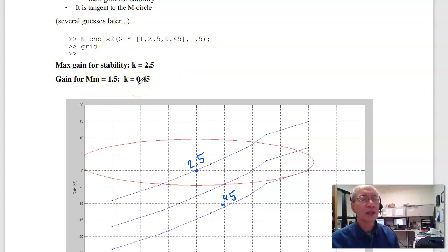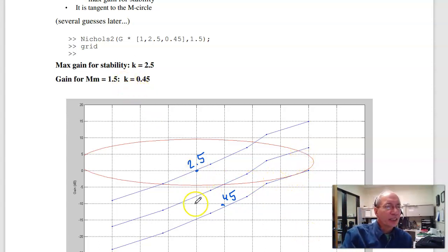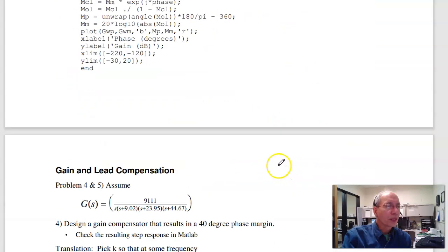Again, this is the beauty of Nichols charts. I don't need the transfer function. I don't need any modeling. I just need a couple data points. In fact, the only data point that I need is 180 degrees, this one right here, for stability, and this point where I'm tangent. If I don't know where I'm going to be tangent, that's why you take a couple points and hope somewhere in this range I've got the correct phase shift. That's a Nichols chart.